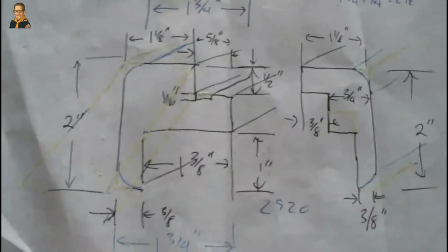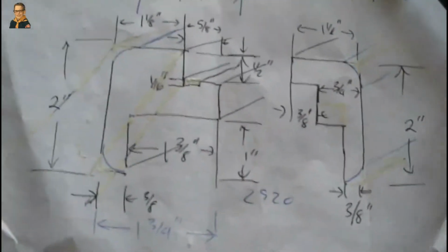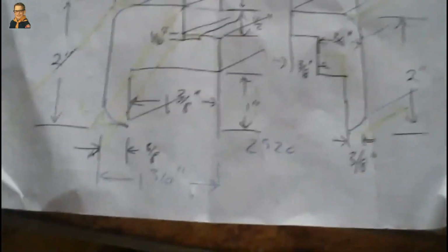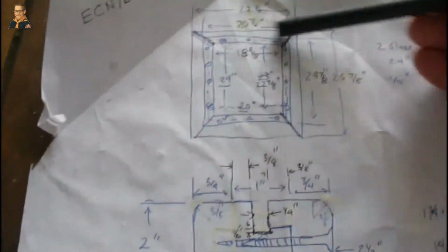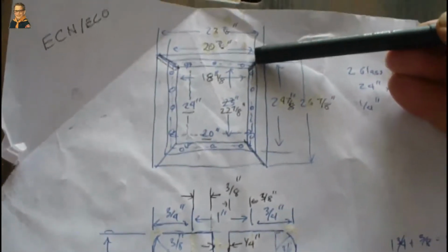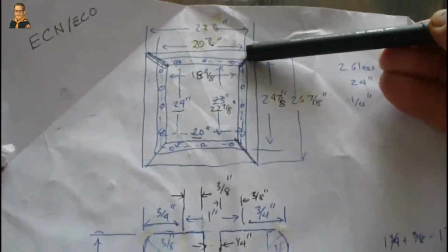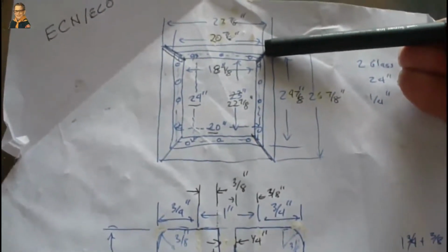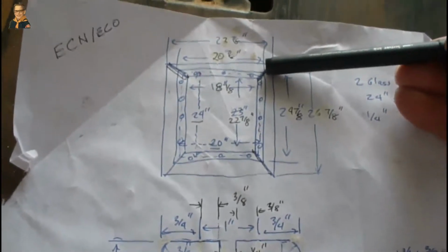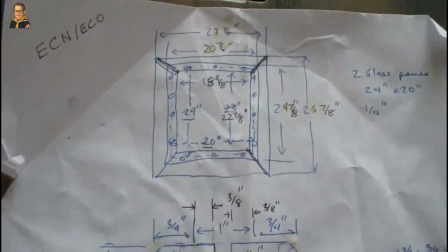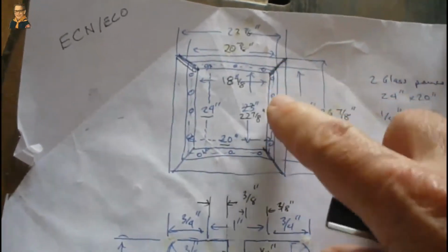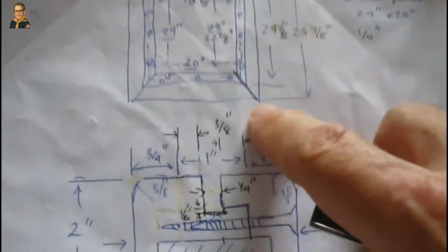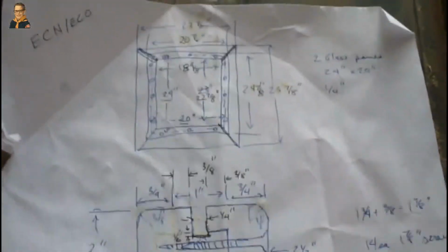As I said, it's a 40-mile drive for me to go to install this window, and I don't want to drive all the way there and find out that I can't fit it in the opening. I know I can drive up there with this exactly 25 and this exactly 21, but if there's any deviation on the existing window opening at all, this piece isn't going to fit. So I decided to give myself an eighth, and the main reason is that I was getting ready to glue this all together, and at the last minute I changed my mind, because once you glue it, that's it.